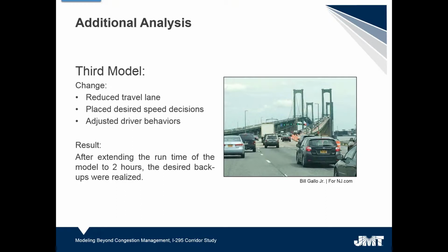So the good thing about creating this model for DRBA is now, let's say that they wanted to do that lane closure in June. Well, they can take that June baseline model that we created, and they can remove a lane, but now they can also take those driver behaviors that we determined in that 5 to 8 mile backup model and apply them to this June model to see what would happen. So now they can have a good idea of what may happen if they do close a lane.